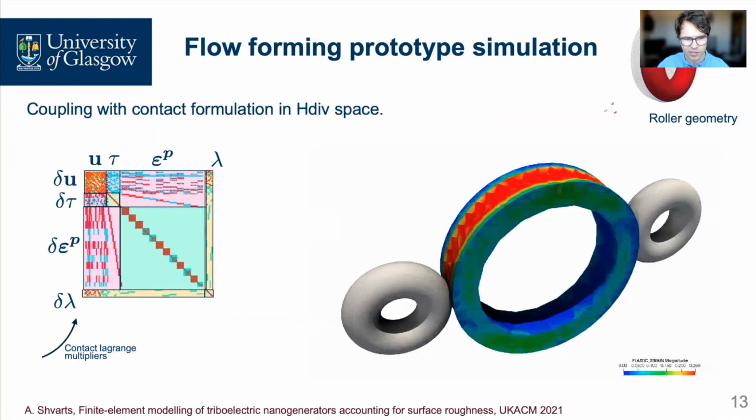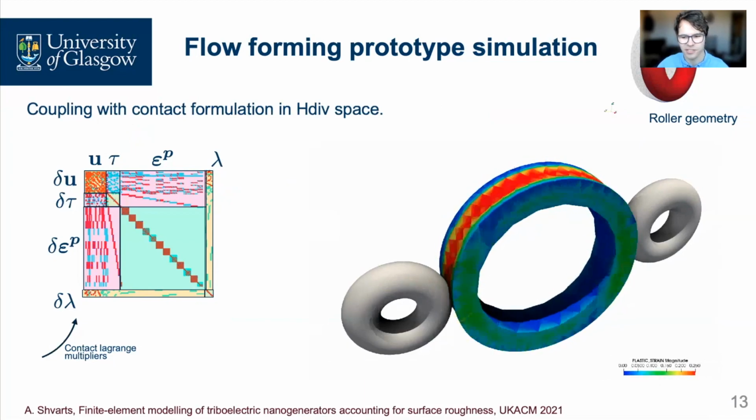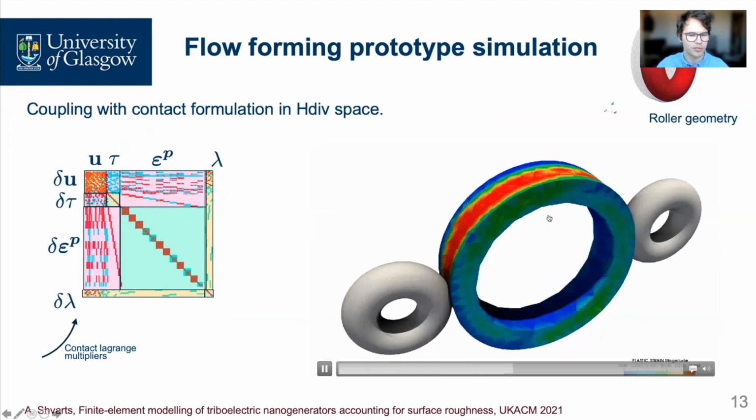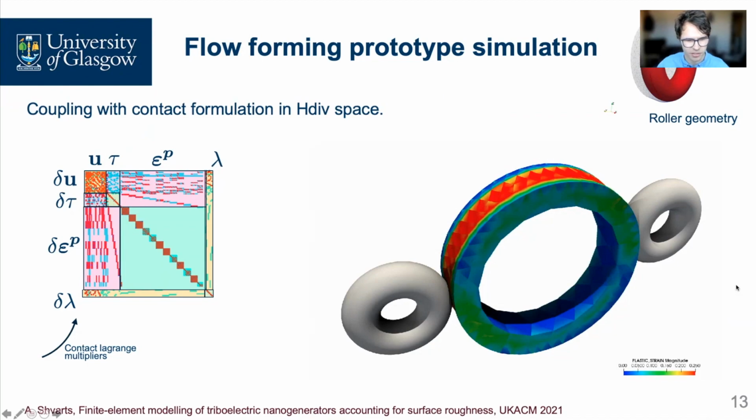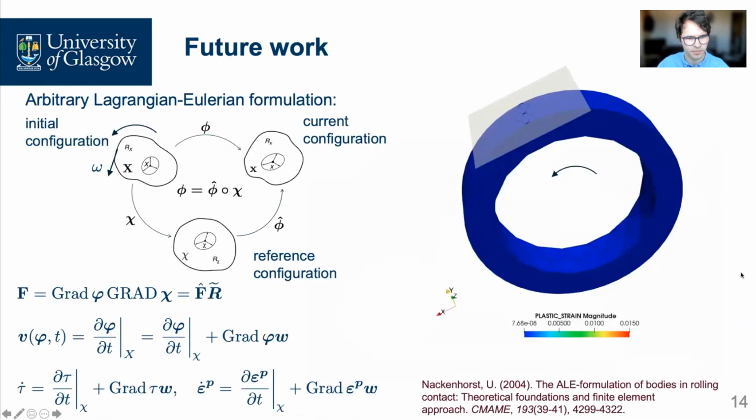This is a small, let's say, toy problem that helps us identify the challenges that we need to face in the future. If we keep rotating the mesh, we will have to use a very small time step and also high refinement of the mesh in the contact zone to preserve the accuracy.